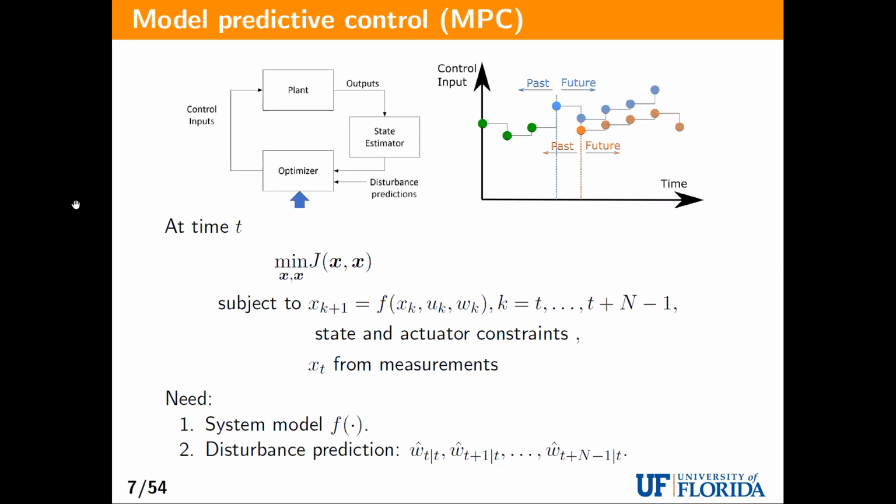So you might have some time-varying control trajectory. So what you do is that you implement the first bit, which might be the first 5 minutes or 10 minutes or even an hour. And then at the next time instant, you resolve the whole thing again, because by that time, things have changed. Maybe you have a better forecast, or maybe the initial conditions have changed. The state estimator might give you something different. Because things have changed, you resolve the whole thing for the next 24 hours. And then you can just go on and on. It's called receding horizon optimal control or model predictive control.